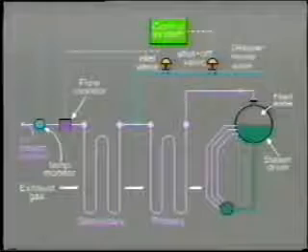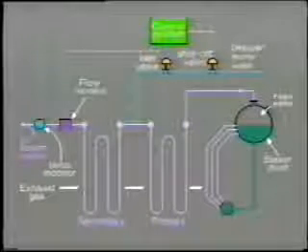Another important trip concerns the feed water supplied to the de-superheater, which, as we know, controls outlet steam temperature. This valve is tripped closed whenever the steam flow to the steam turbine falls below a predetermined minimum level. The reason for this is that with minimum steam flow, the de-superheating water, instead of evaporating, may be carried on through the steam turbine and so cause internal damage.